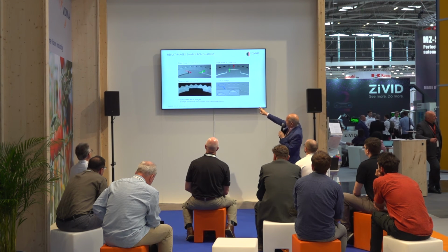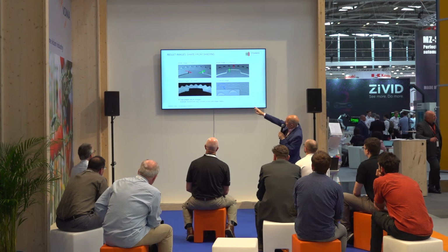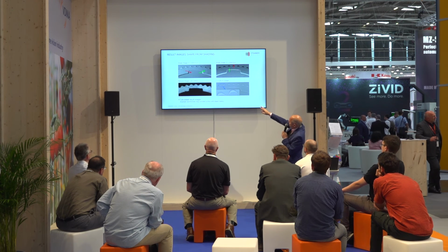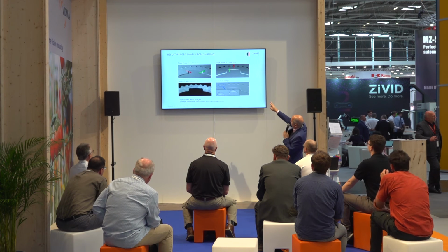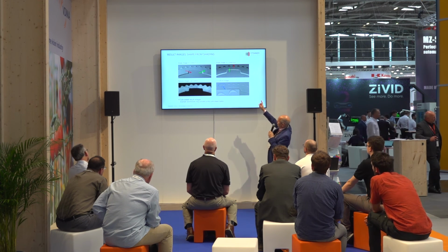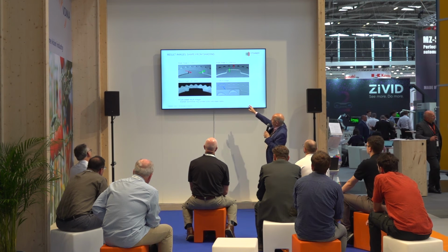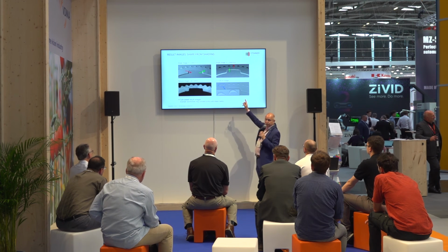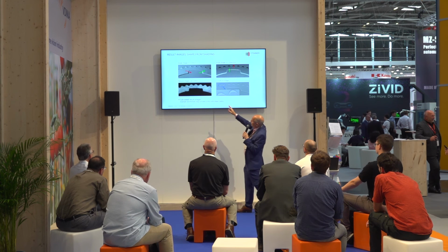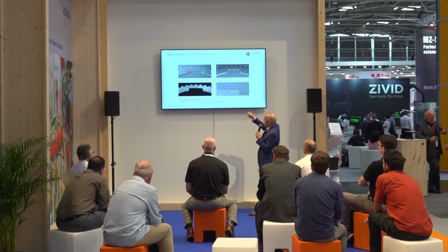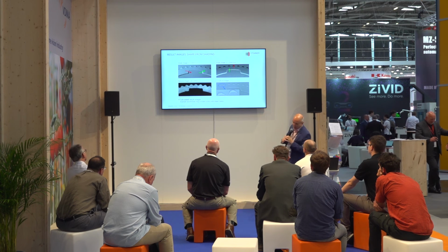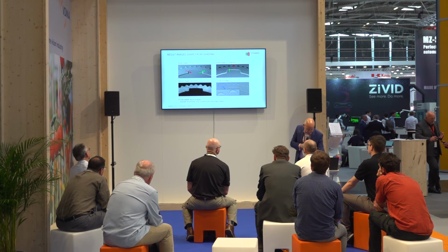On this curvature image, if you can see here on the left, we are looking at the slope, the first derivative, in one direction. On the second, we are looking at the other direction. We process that and look at the second derivative, and we can really start to find very small, fine defects on that surface. And we also can, with the texture, calculate contamination defects and variations on it. So it's pretty powerful there.